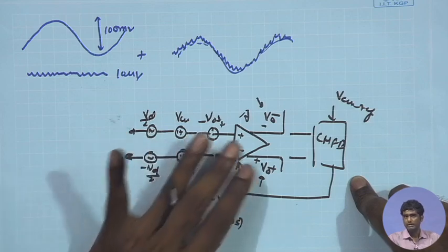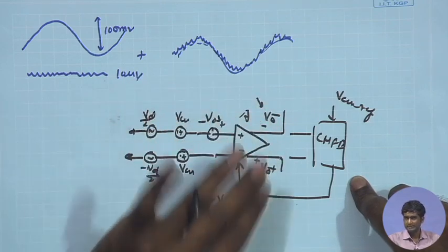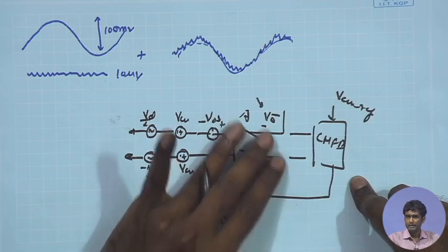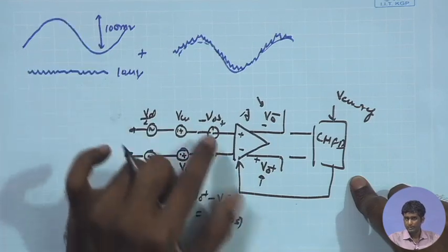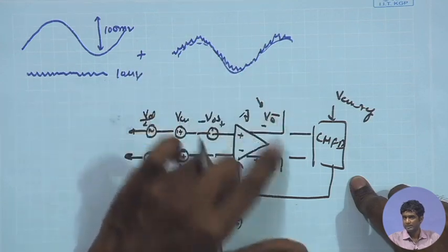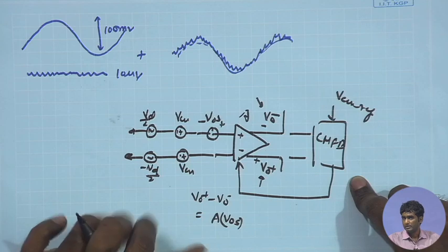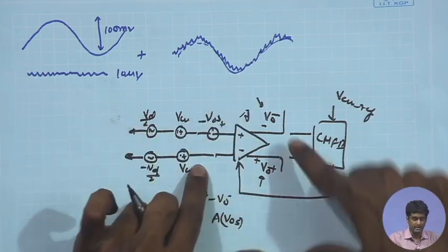Even if you are having a feedback amplifier where you have the feedback circuitry, suppose resistive feedback or capacitive feedback connected, if I assume resistive feedback, in that case once again the offset voltages over here can create large deviation in the output signal, and the outputs can saturate to high or low value even for a small offset voltage over here.